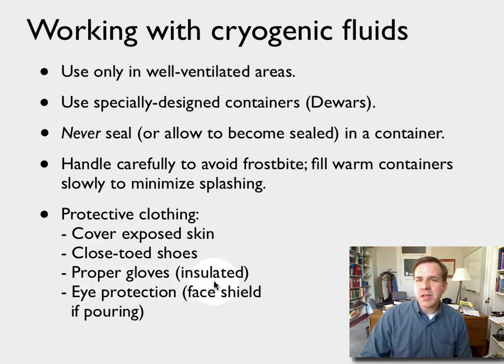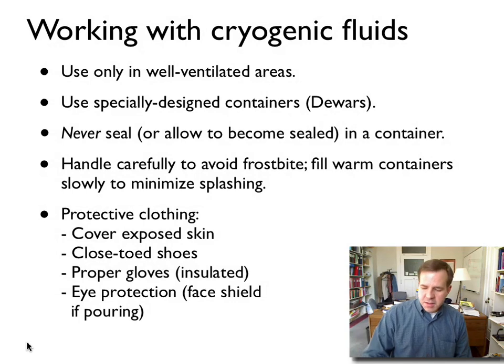There are special insulated gloves for dealing with cryogenic fluids, which we should always wear when transferring fluids from one container to another. And finally, you always want to wear eye protection, because if there's one place in your body where you don't want to splash a cryogenic fluid, it's into your eye. And in particular, if you're pouring a cryogenic fluid with the attendant risk of some splashing, then a full face shield is strongly recommended for that process.